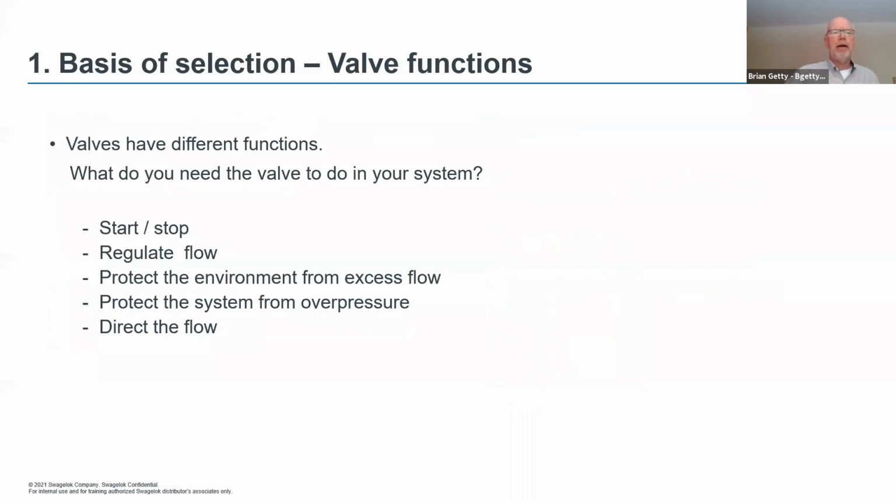All right, here, your valve functions. All of the decisions that we're going to be making for the selection of a valve start with your first decision. Well, what do I need to do with this valve? Is it to turn a system on or off? Do I need to have overpressure protection? Do I need to make sure we don't have excess flows in the event of a breakage in the system somewhere? Is it to regulate flow? Do I want to regulate the flow, or do I need to direct the flow, send the flows into different directions? This is where the selection of your valve starts.